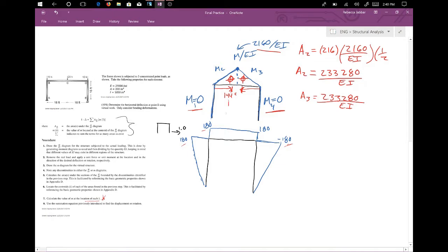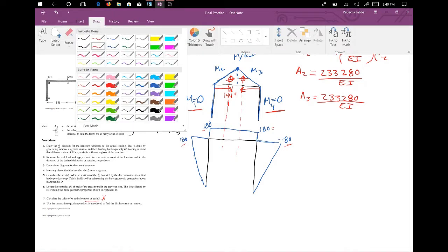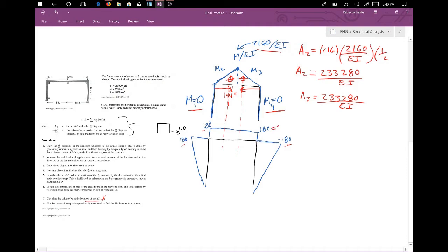So that's why I tried to line up both of these frames. What we would do is just follow this all the way down, and it actually doesn't matter where our centroids are, because the value of our little m is the same throughout that top member. And again, these guys are 0, so they have no centroid location. We're just ignoring them. It's still good practice to do, but even these guys won't do anything for us at this point, and we're only looking at these top members.